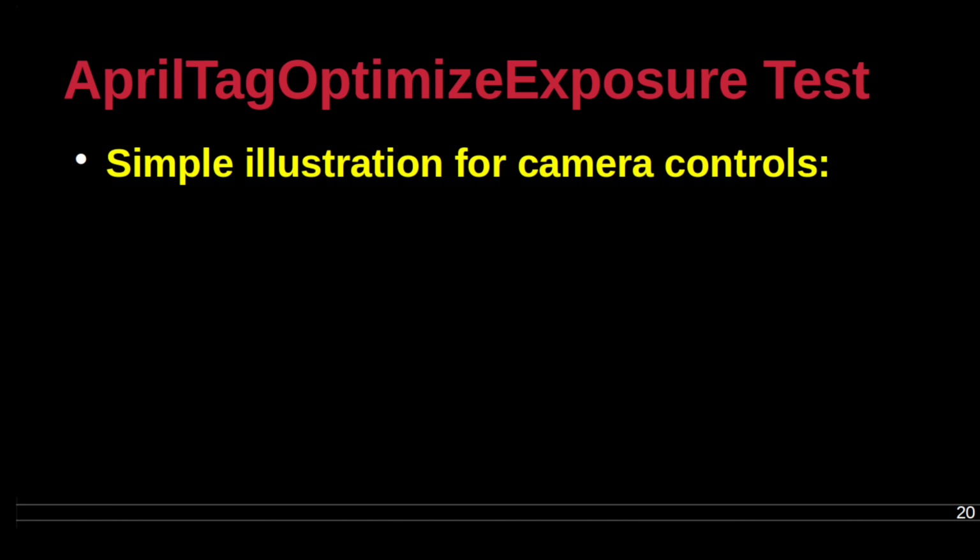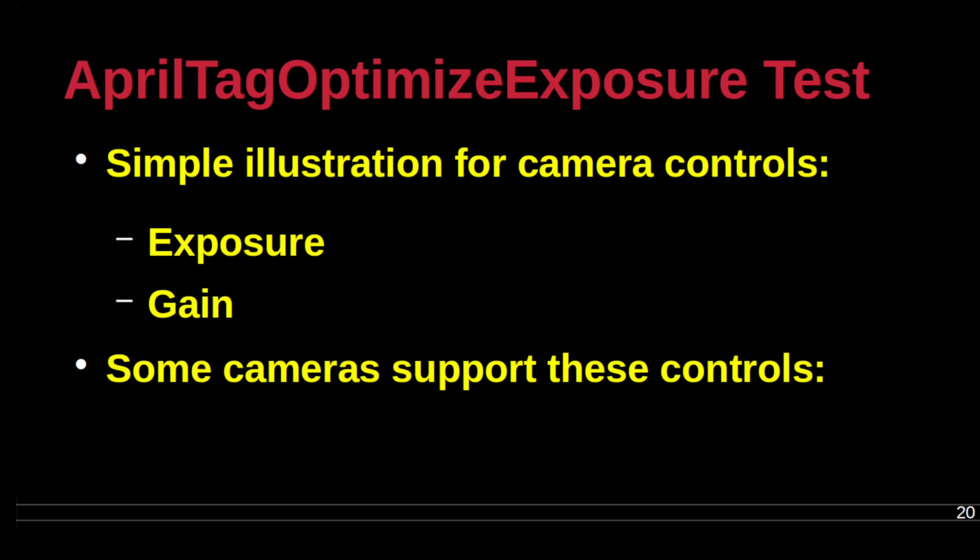The properties of the camera with respect to exposure and gain can be set in this Opmode. The bumper and trigger buttons on the gamepad increase or decrease the values for exposure and gain. While the original example initializes the value of exposure and gain to minimum values, it is best to use midpoint values as the initial settings.